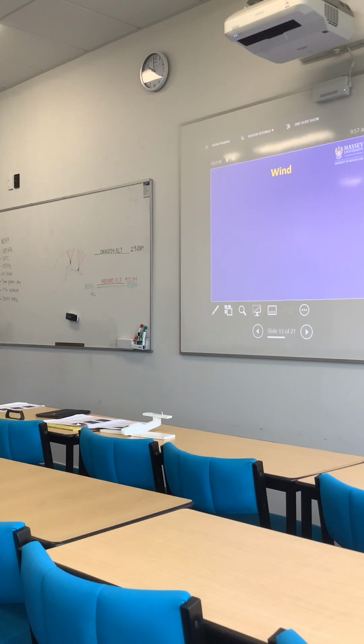And it's going to take a longer distance to get to that speed. So what do we want? We want to take off into wind. Not only does it reduce the takeoff distance required, it increases the climb performance as well. Obstacle clearance, and that's an important factor for this briefing today.